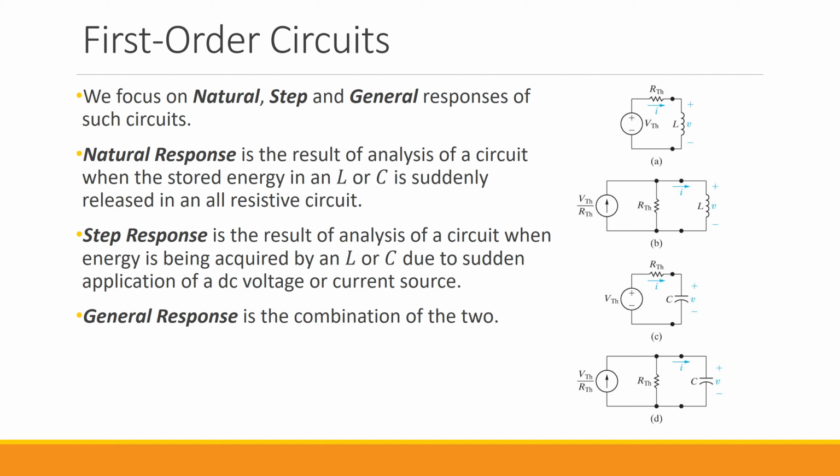The step response is going to be the result of analysis of a circuit when energy is being acquired by an inductor or capacitor due to sudden application of a DC voltage or current source. So here, in addition to the resistor, we have a source as well. But this time we don't have any initial voltage for the capacitor or any initial current for the inductor.